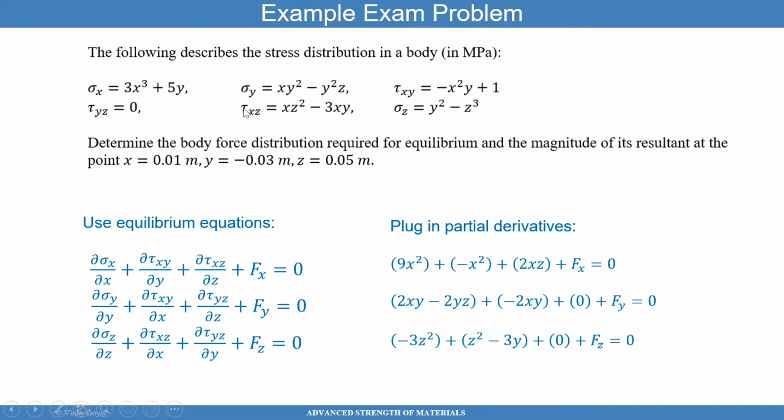I'm using tau here, but they're used interchangeably in the literature when we refer to shear. Finally, sigma xy equals sigma yx because of the stress tensor being symmetric. Sigma xx, sigma yy, and sigma zz represent the components of stress normal to the surface of a cube. While these components are tangential to the surfaces of the cube, causing the cube to distort.